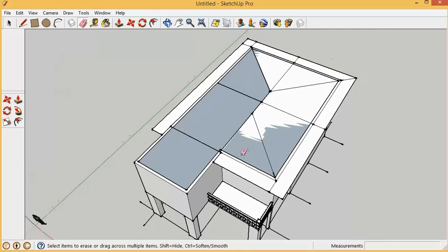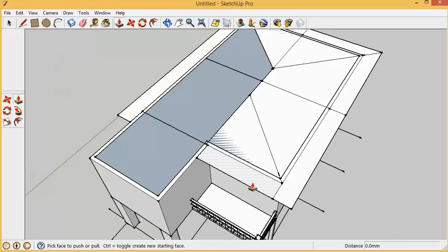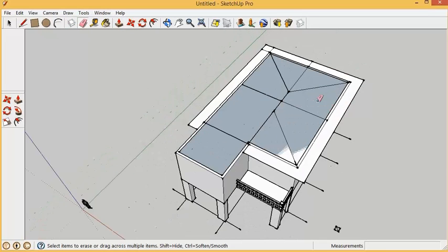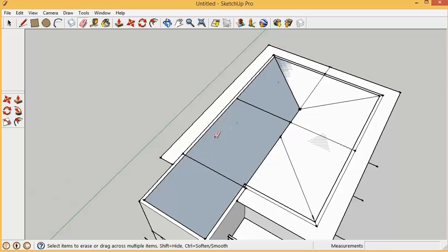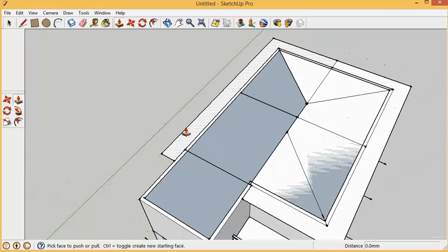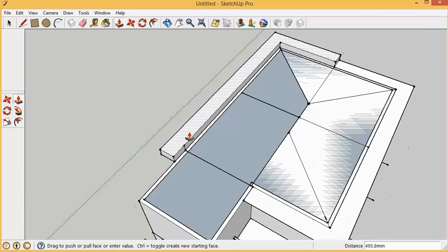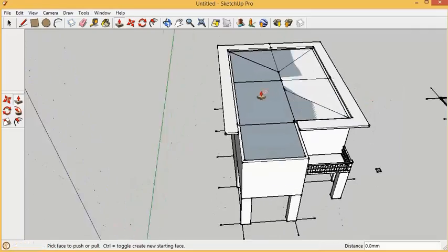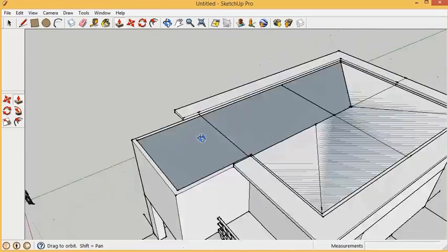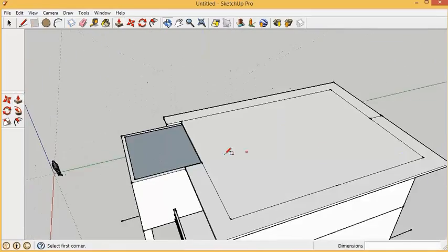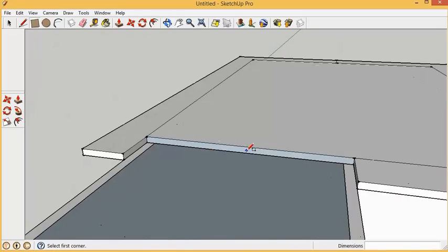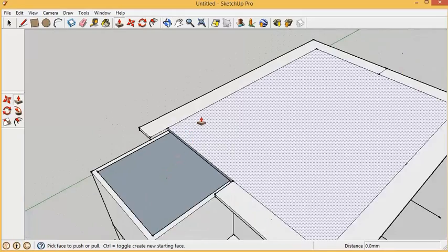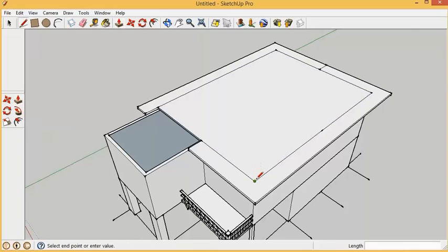Now, another important thing is that you can actually change the scale of the texture. These bricks here are a little bit small, but if we wanted to, we could make them bigger. Right now it says that the texture is 3 feet by 1 foot 6 inches. This can be very useful when you start using guidelines to help you draw. I'm going to go ahead and lock here, which locks or unlocks the aspect ratio. So this is locked. Let's go ahead and just change that back to 2 feet. So as you can see, we can also change the scale of that texture.